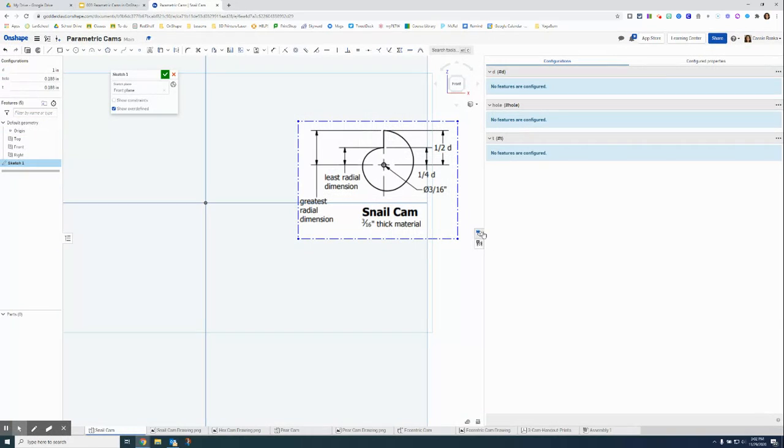And I went ahead and added in our configurations, just like we did the last few times, where I have D being my diameter for one hole. I set it for 3/16 of an inch. And then T for thickness, that would be my extrusion depth. So we've done these a few times. If you don't remember how to do this part, I would hop on to another video, watch how I set up the parameters, and then hop back on over here.